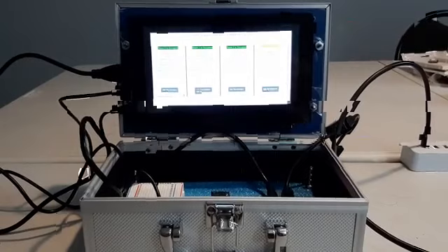First of all, the damper is fully closed. You see the damper opening is 0%, and the damper opening percentage is 0. I will show you how the damper works in manual mode, and then I will show you how it operates in auto mode. So first of all, we can put the mode of the damper to on mode. I click on this off, so it goes to on mode, and it's ready to give the damper set point.